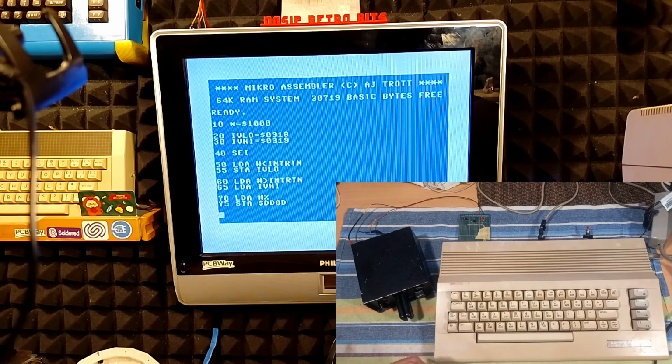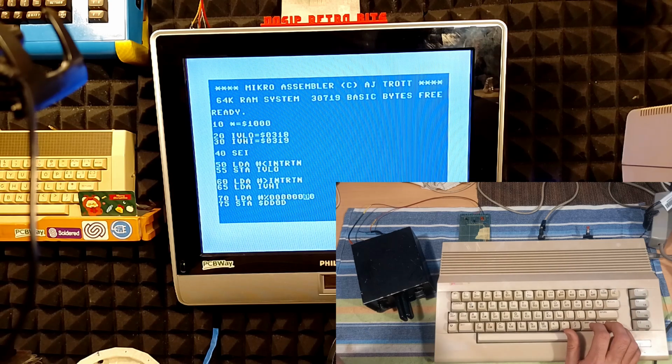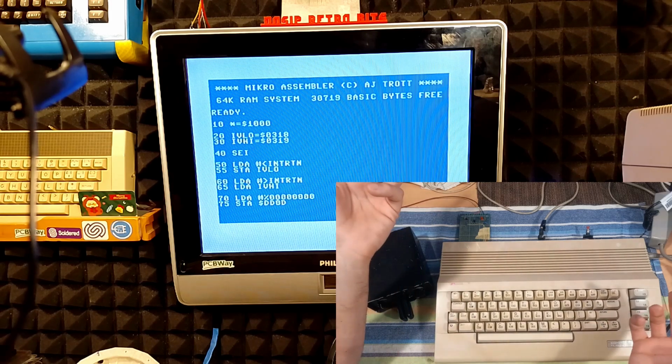Now this register is the CIA2 interrupt control and status register. That means it behaves a little bit differently than we are used to. So let me write here 8 zeros: 1, 2, 3, 4, 5, 6, 7, 8. The first 5 bits of this number, from bit 0 up to bit 4, behave like a mask.